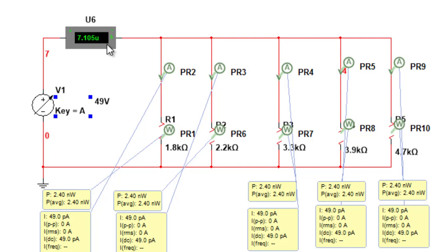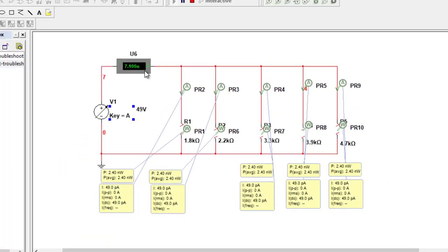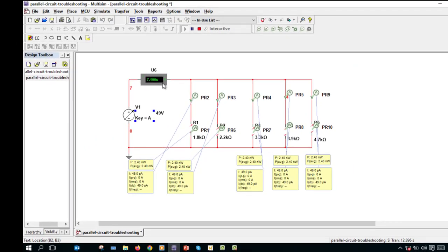So we can see that the wattage of the resistor is 0.5. Once it gets to the maximum current and you exceed it, it blows up. For us to repair it, since it's R1 that's burnt, we can increase the wattage to maybe 1 watt, so it will last more, or we adjust the resistance value so that it will not reach the maximum current it's supposed to carry.